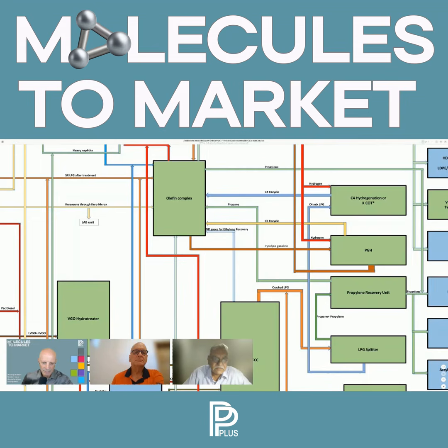Project cost, as I said, infrastructure cost is one simple site element. Utilities and offsite facilities, based on the input which is coming from the licensors, are all preliminarily assessed by the consultant. And we can do the sizing of, let's say, raw water system, cooling water system, instrument and plant air, nitrogen, all these systems, and work out the costs for those. So that can be the other setup. This is how we put together the cost.